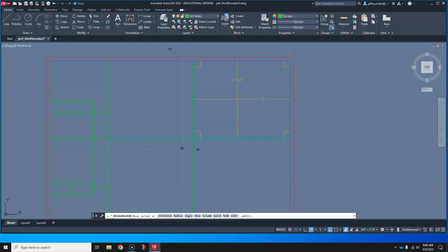Okay. So, master bedroom, we need a closet. There's all types of closets you can put in a master bedroom. You can put just a regular 2-foot closet right here, like we have here. Now, 2 foot is the minimum. You don't want to go anything less than 2 feet. 2 feet is the minimum width of a closet, okay? Now, they can be as long as you want them to be. From wall to wall, they need to be 2, or depth, I should say. The depth should be 2 feet.